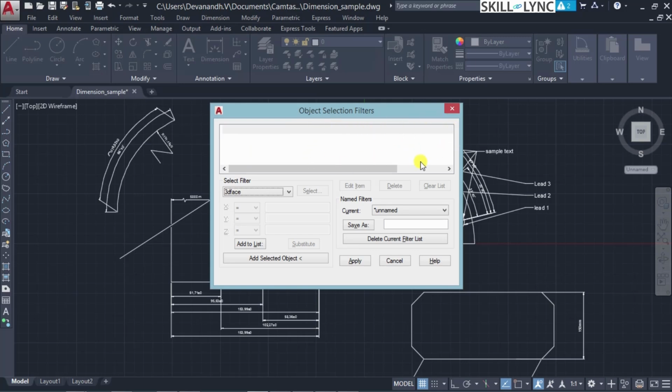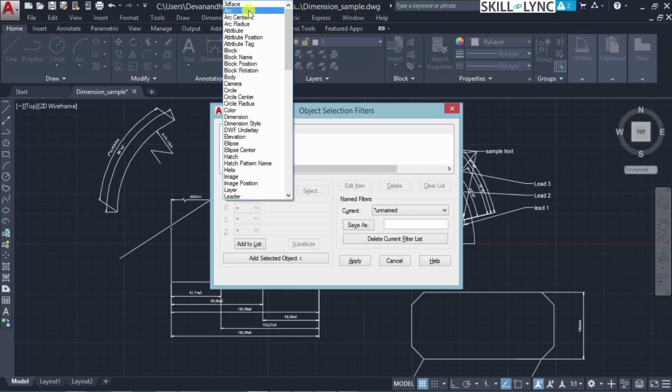In order to populate the list, the first option is to select the type of filter that you need. Here you can see the different properties or object behaviors that can be selected from here. Towards the back end of this, you also have different operators that are available. These are called the Boolean operators, and here we have AND, OR, NOT, and also exclusive OR. These four Boolean operators are prefixed with commands called begin and end. We will look into that command separately.